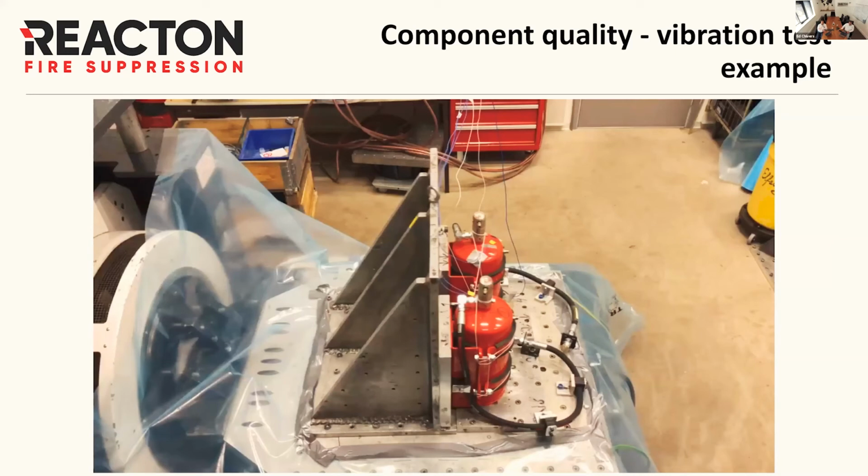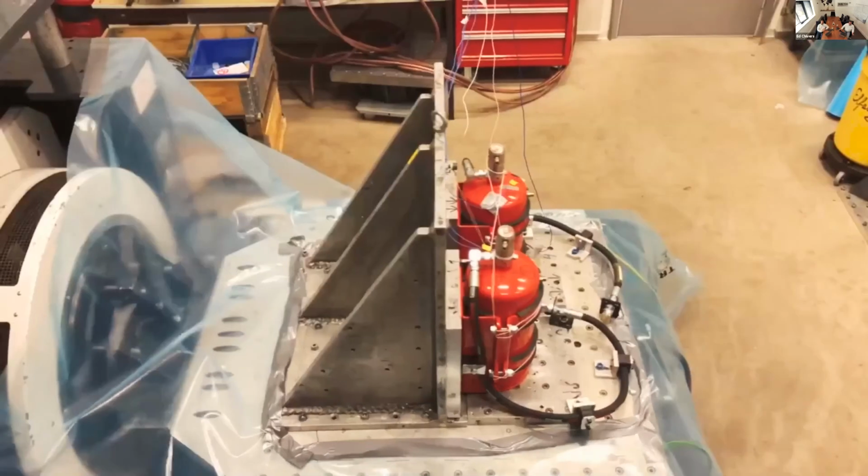And the systems are on this for 96 hours. And that's after they've been temperature cycled from -40 to +80. And even after all of this, they then go through 5,060 shocks at 10 and 20 G. And then you have to discharge the system and ensure that you get enough of the contents out. Just to give you an idea of the performance, our 9-kilo cylinder, after all of this extremely harsh treatment, discharged all the agent apart from 6 grams of powder, which just shows you how effective it is.